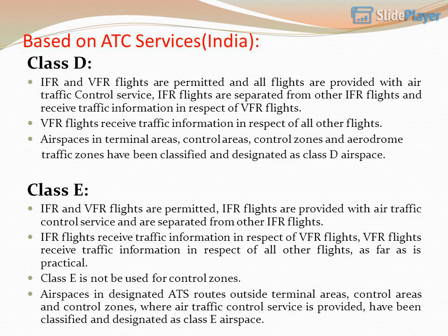Class D. IFR and VFR flights are permitted and all flights are provided with air traffic control service. IFR flights are separated from other IFR flights and receive traffic information in respect of VFR flights. VFR flights receive traffic information in respect of all other flights. Airspaces in terminal areas, control zones and aerodrome traffic zones have been classified and designated as Class D airspace.